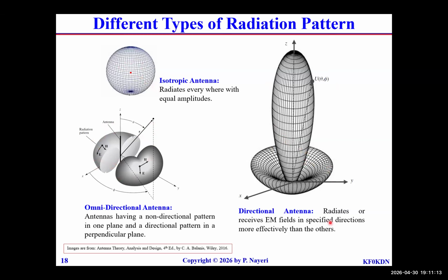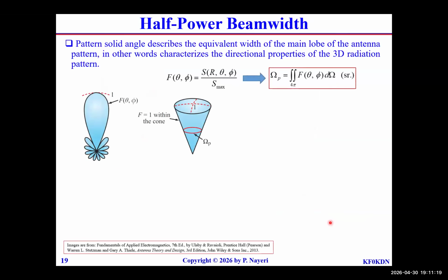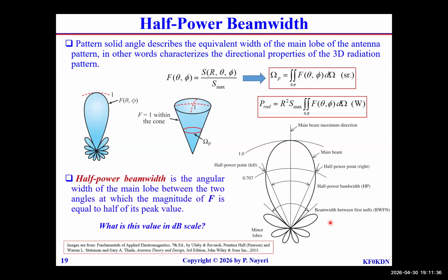As you can see, they point the beam in a very accurate direction. Depending on the size, those would be impacted. But just so you know, with large spherical reflectors that are used for some applications, we can have half power beam widths in the order of 0.1 degrees. So that's extremely highly directive and of course has its own application.